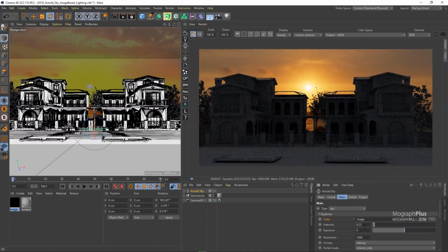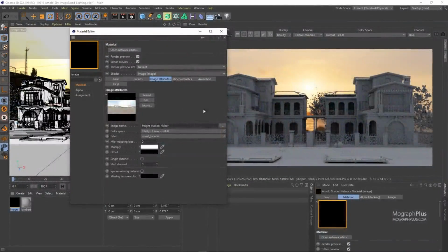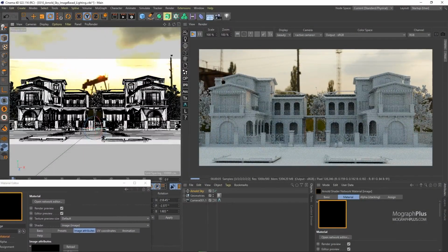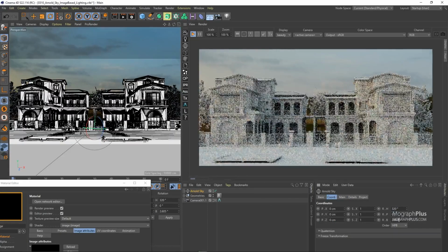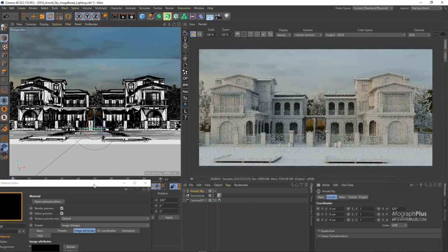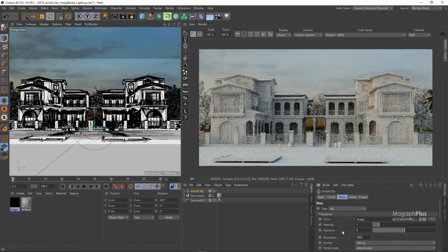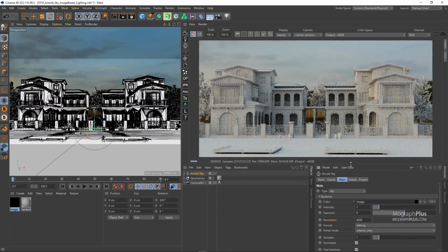Let's use another HDRI. You can load this Fright Station HDRI, which is a free HDRI from hdrihaven.com, and set the rotation to around 320 degrees probably. And now we get a completely different look, which is incredible. Then we have resolution, which we discussed, and you should set the resolution close to the actual resolution of the image. The HDR I'm using is about 4000 pixels wide, so we can type in 4000, but for faster renders, let me just leave it at 1000 for now.